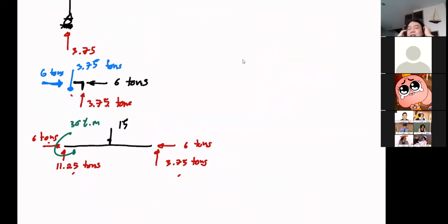So that is the free body diagram of member BC. You can try to take moment at C right away to check whether or not your MC is 0, and it better be. And let's do it now. Sigma MC equal to 0. So you now have 11.25 multiplied by 8, minus 30 minus 15 multiplied by 4. That's 0, folks. Can you check it for me?